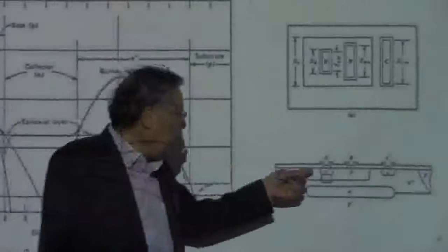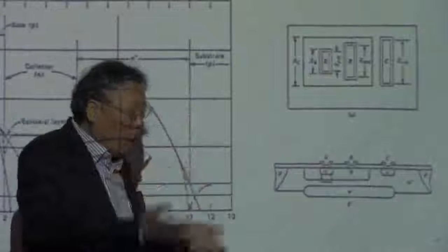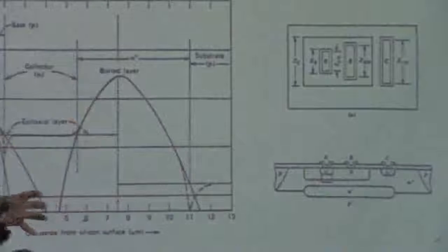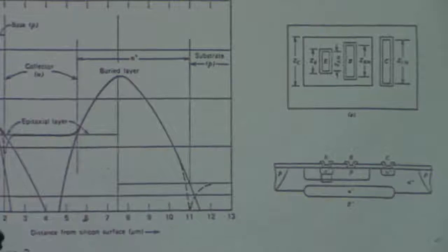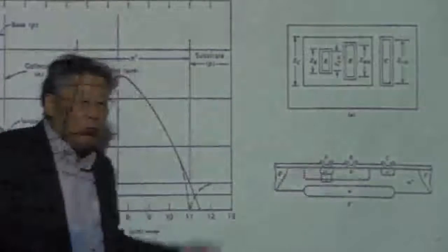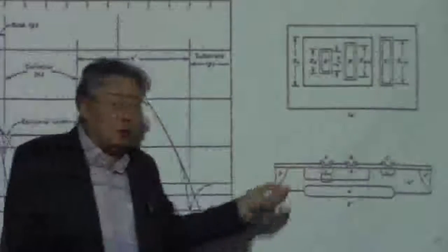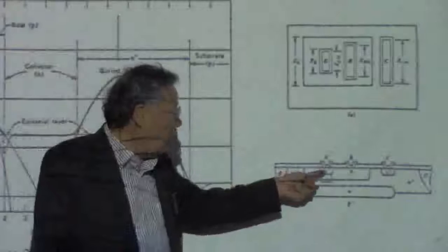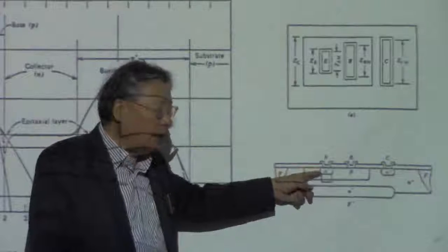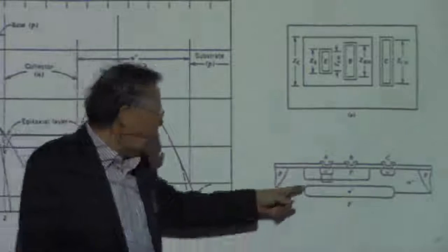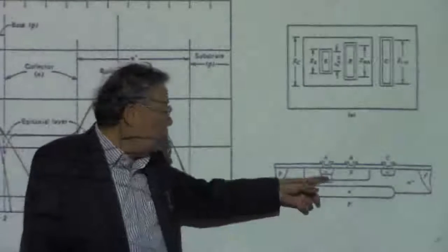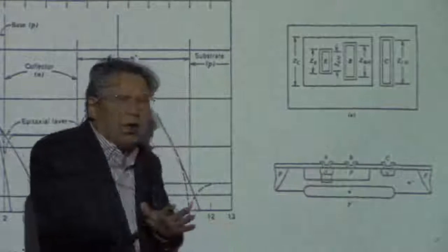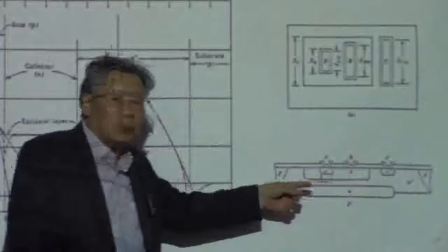Because the arsenic has a low diffusion coefficient, the junction depth cannot be big. We need a shallow junction for the emitters. So we have to use the arsenic, and we have a choice for the phosphorus for that, but you have seen in the early chapters of our class that if you use the phosphorus for the N plus, we have an emitter push, okay, vacancy generation underneath the emitter, so that this boron is going to be diffused a little bit farther than is expected from the Gaussian profile.